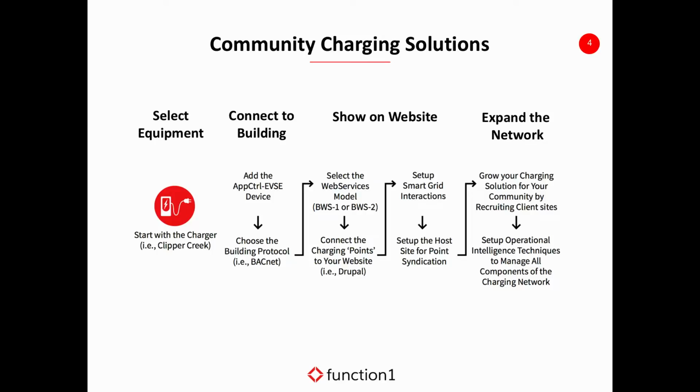So the interface device is what I have right here. And this is what we developed specifically for Drupal. This has what's called the BACnet vendor ID number, and I talked about that in the lightning talk that we did yesterday. You can go to the BACnet.org site and find the BACnet vendor ID number for Drupal, which is number 751.